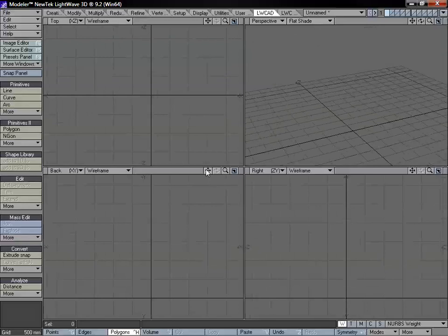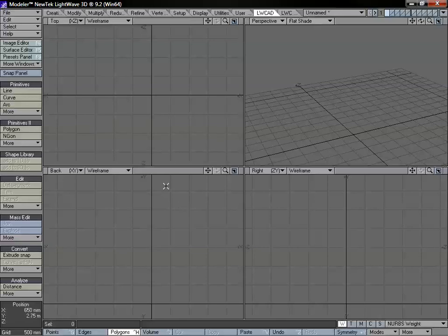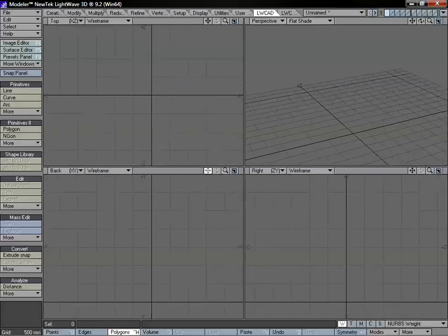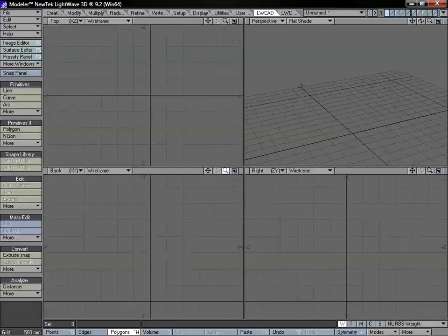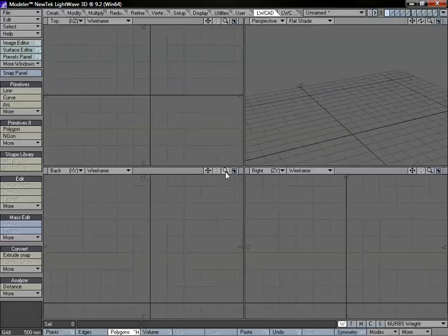Now the first thing I'm going to work on is the sections of the fence and the actual fence itself, and then we'll do the posts afterwards. One thing to keep in mind is that you do want to keep this basically in the correct measurements, especially with the fence tool, because you're really not able to change its size very easily, at least not as easily as you would with the window and the door tool. So typically when you're modeling fence objects, you want to make sure they're the correct size.